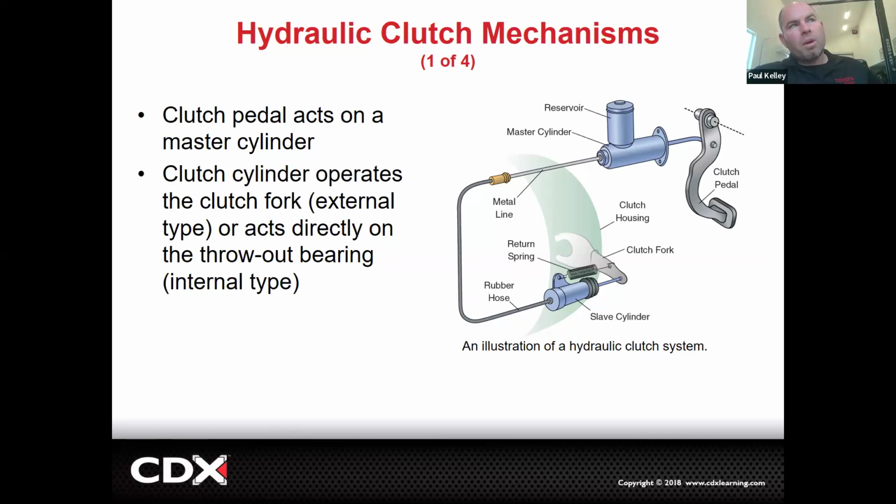Okay, now what about another one? Hint, hint. This is behind me now. If we have, let's say, a 1/2 inch of air in this line, we throw the clutch pedal 6 inches. This master cylinder strokes 1 inch. The fluid only moves a 1/2 inch because there's a 1/2 inch of air that gets compressed. So therefore the slave only moves a 1/2 inch. That would be grinding as well. That would be dragging. Makes sense?